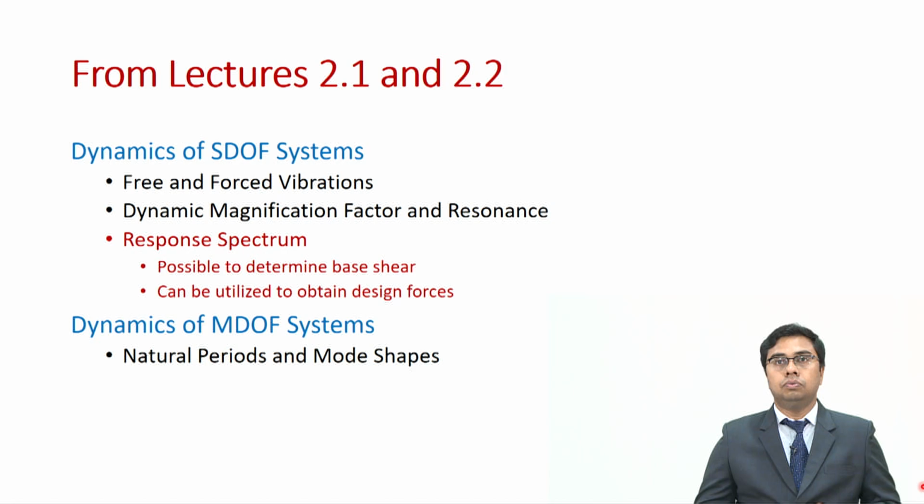part 1 2016. In lectures 2.1 and 2.2, we did look into dynamics of single degree of freedom system, where we learnt about free and forced vibrations. We also looked at dynamic magnification factor and resonance, which is an occurrence when the excitation frequency is equal to the fundamental frequency of the structural system. We also looked into the concept of response spectrum, through which we understood that it is possible to determine base shear and can be utilized to obtain design seismic forces.